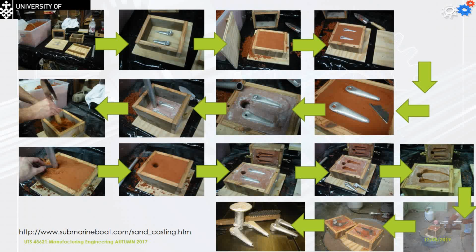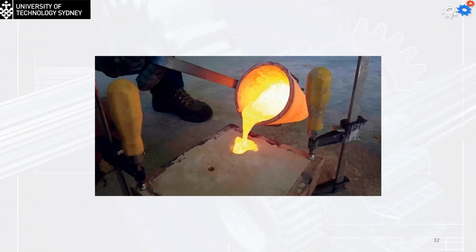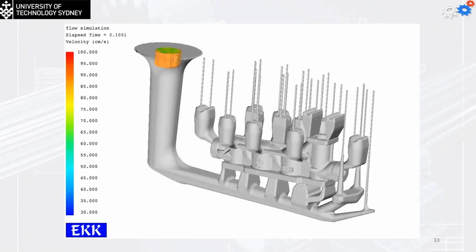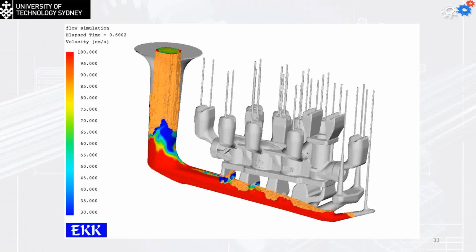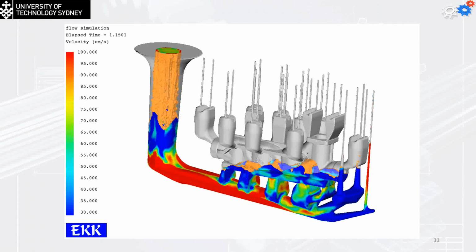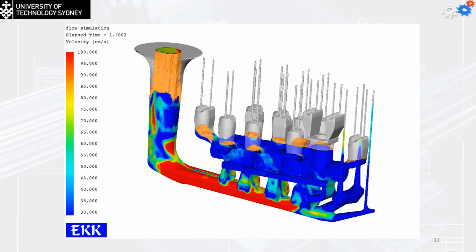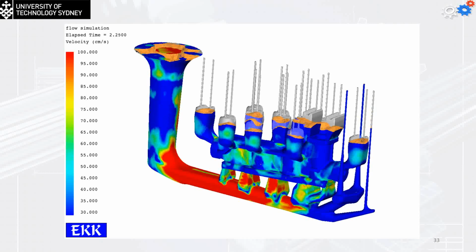So that's how to pour the metal. We have this cavity for the riser. Otherwise, the air will be trapped in, and this will resist the filling of the cavity. Okay, so now these are the escape for the trapped air. So we're not going to have any cavity within the cast part. So a different shape has been done by the casting.